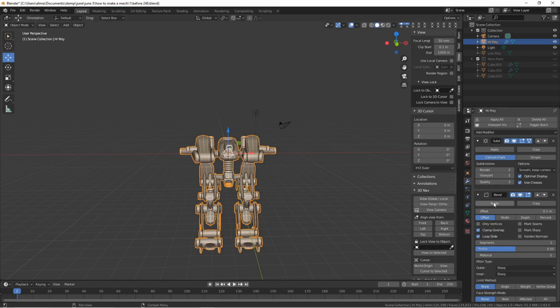It's because of the order of the bevel modifier in the stack of modifiers here. Here's the subdivision surface modifier. This represents the subdivision surface modifier. This is the bevel modifier. See these arrows here? We want to put this bevel modifier above the subdivision surface modifier, so I'm about to left click on the arrow. That should make things look much better. So I'm left clicking.